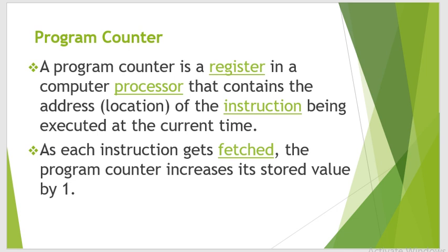The first point is the program counter. The program counter fetches the address of the next instruction. The program counter starts at 0 or 1 at the first execution of the program. When it executes the first instruction, the program counter starts at 1. Then for the second instruction, or second line of your program or subroutine, the program counter is incremented by 1, up to the end of the instructions. It is incremented each time.